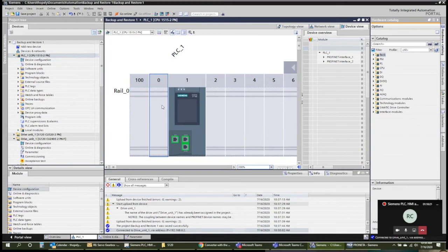Okay, no, appreciate it. So Terry, for our drives, our Ethernet drives are Profinet and Ethernet IP kind of combos, right? You can just pick one or the other. I don't know if the Rockwell Ethernet drives are Profinet and EIP, or if they're just EIP. I'm guessing it's just the latter, but I don't know that for sure. I'm in the same boat as you. I don't know for sure. I don't think they support Profinet, at least on many of the devices anyway. Most of the other manufacturers' drives, though, do have a Profinet communication capability, I think, as an option. Correct.